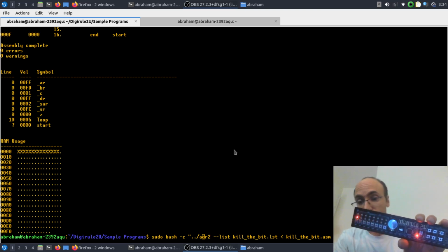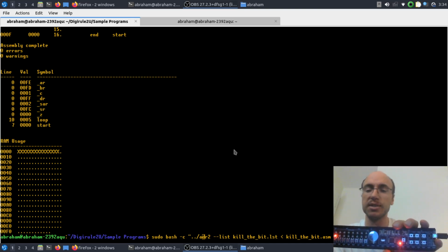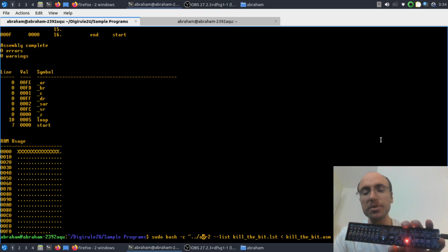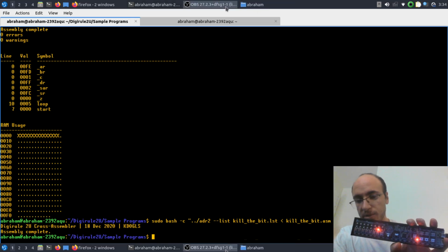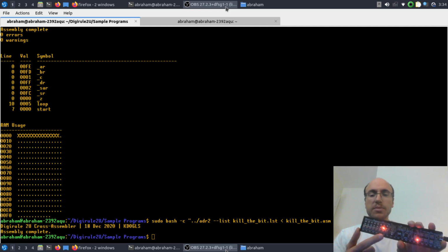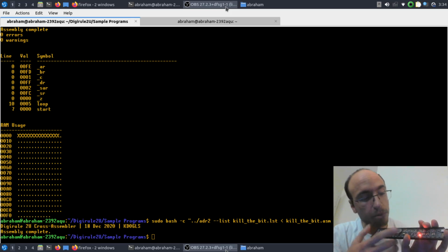And later I'll go ahead and show you the part of the manual that describes the status LEDs for loading and saving programs from a PC. And now that I have that in load from USB mode, I will load the program from USB. And we should see that the blinking light is no longer blinking, and there's another light that's solid there. Okay, so now let me go ahead and get this back in run mode.